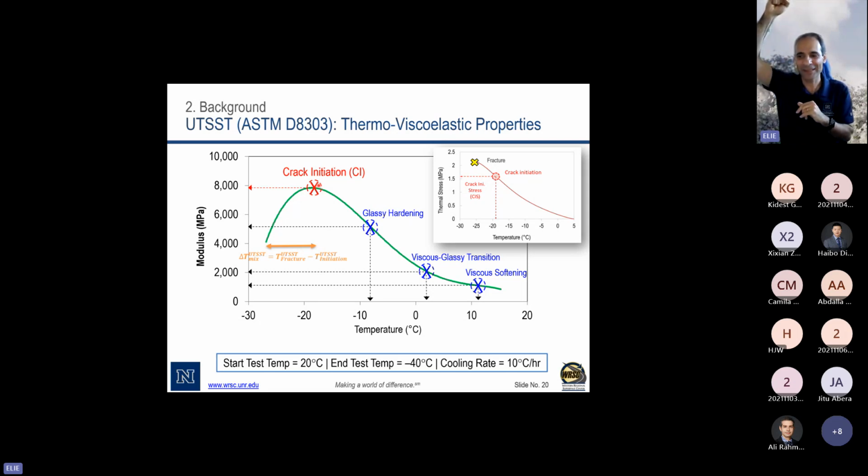They're very stiff, but they don't have tolerance. They don't have any strain tolerance. The minute the crack initiates, it fractures. So that is telling us a lot about the mixture behavior. And this is where we can take this and translate it into the thermal stress curve, and we can see at what temperature, what stress, and at what strain level that occurred.